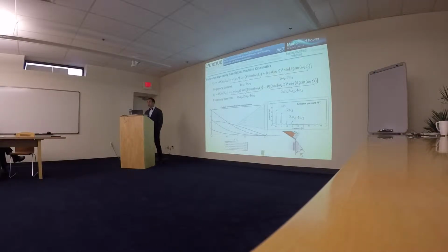But as we will see in the result, unfortunately, the payload oscillation is exactly the frequency we want to move the machine at in order to stop the payload oscillation. So it's something that we are going to affect with the control of the machine, so we cannot directly use this information. While 2 omega 2 is something that we can use, because we are not affecting this frequency directly with the control of the machine. This is explained much better in my thesis; here, for time constraints, I'm not explaining the whole process.